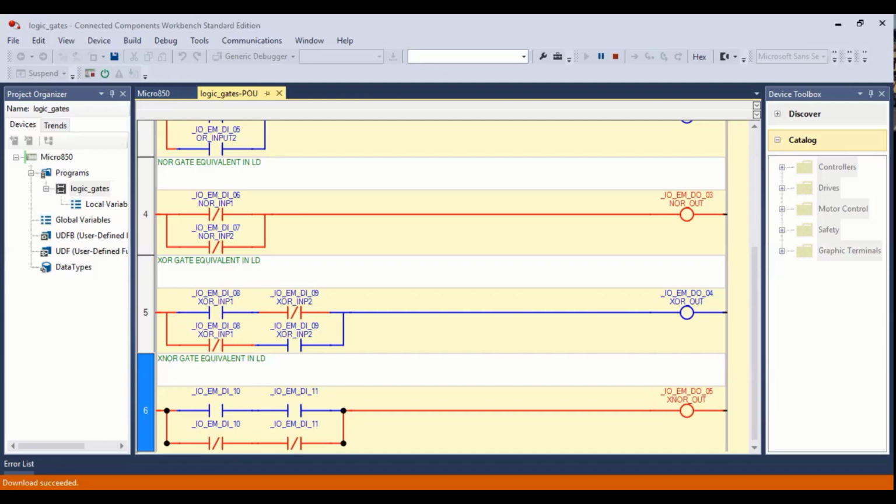I think that's going to be brought up in one of your tutorials, but you can warm up trying to think about, how do I do this ladder program that will run this motor control? Right? My IOs are the start, the stop, my motor itself, pilot light, system off, pilot light, system on. So three outs, one in. How do I automatically implement that here in ladder logic?